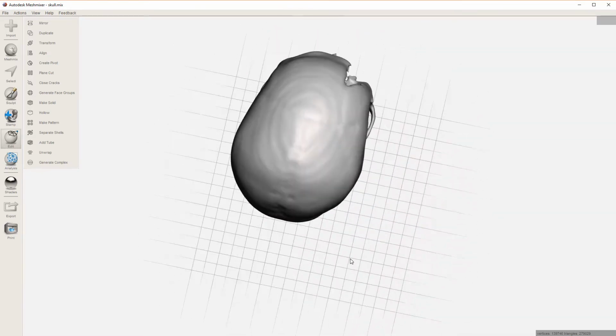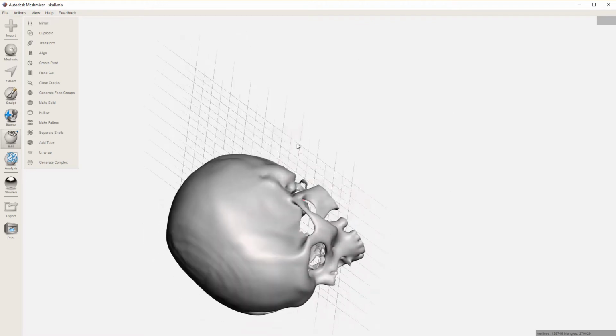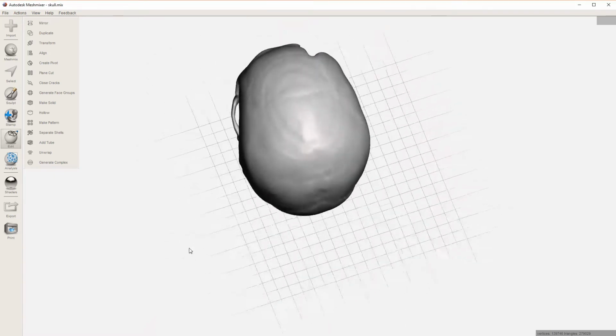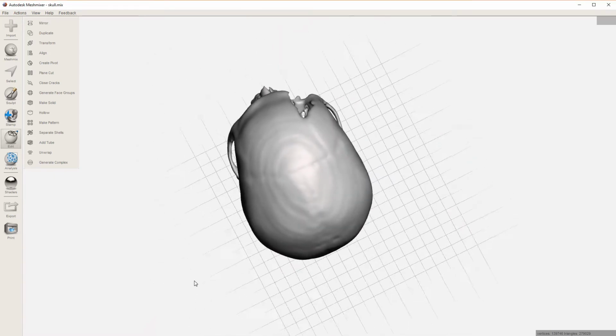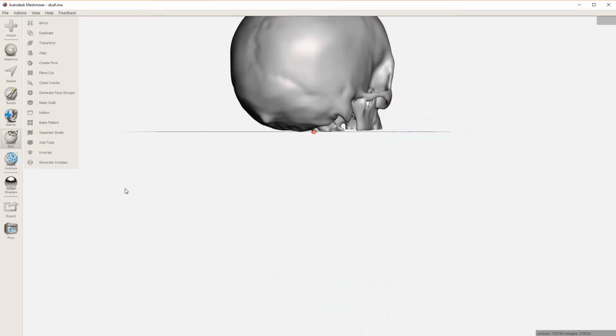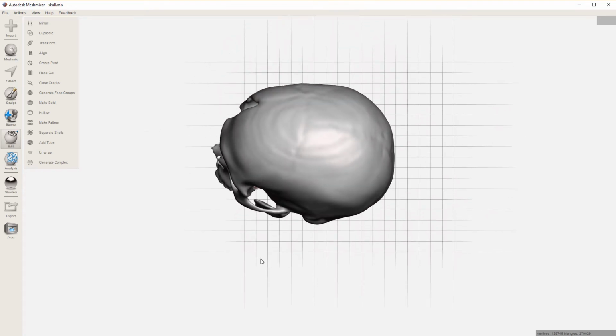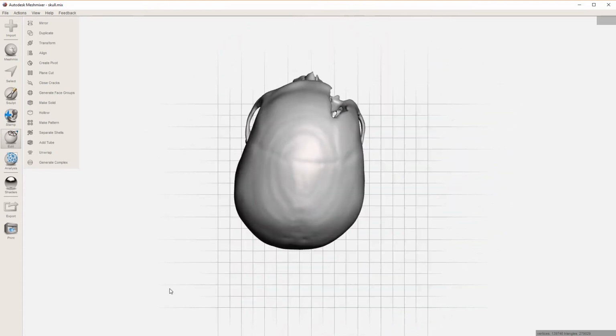One nice thing also when we're working with this is that you can turn on snapping. If I hold down the space bar, these two things are shaded, which means I can go anywhere. But if I turn these off and I say just snapping becomes shaded in, now it's going to snap. You can see it going click, click. When I go like this, it clicks into various views at a 90-degree increment in all directions. So that's very nice to look at this straight up.